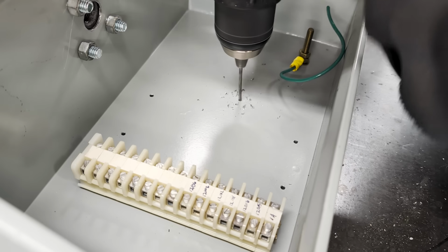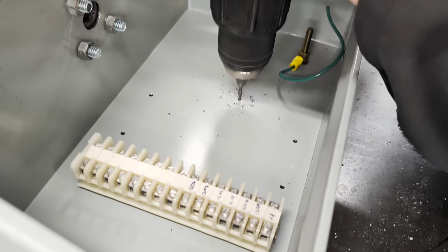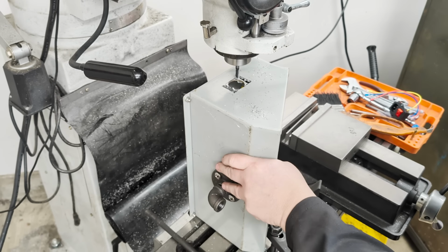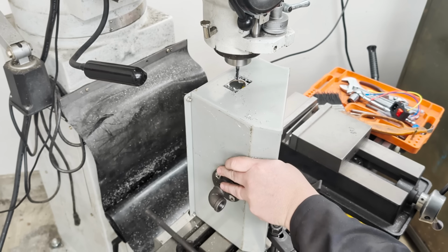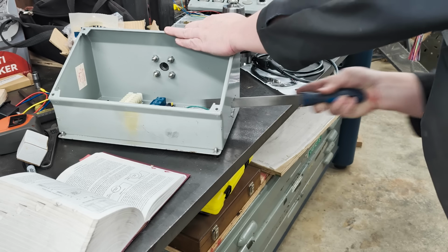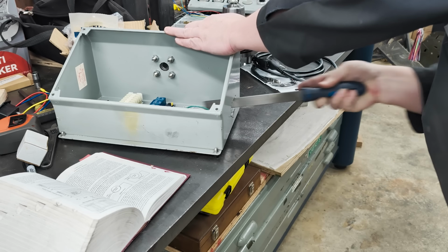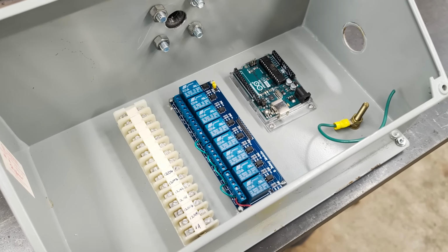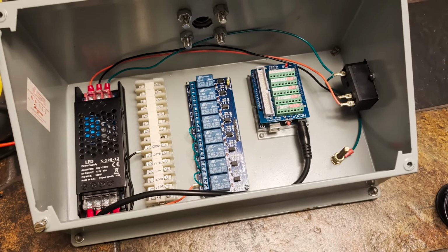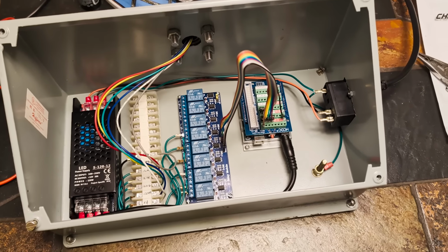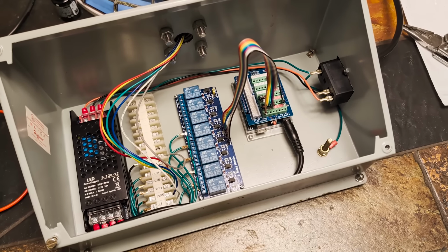Wiring wasn't too hard, just the hassle of mounting all the components inside first. I also enlarged the existing hole in the side for a power socket with a built-in switch. There wasn't a good way to mount it to the mill though, causing enough chatter to break the 1/4" end mill I was using. Whoops. But I was able to finish it up well enough with a hand file. I decided to keep the terminal block that came inside the control panel, as it will provide a convenient way to attach and detach the stack light wires. That way I can disconnect them fairly easily when I remove the mast for transport.